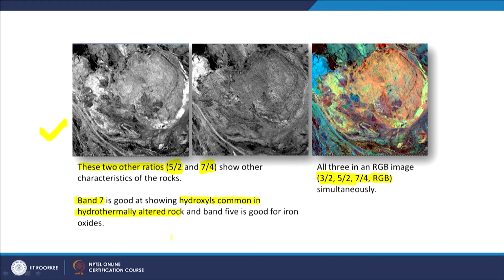Recall when we were discussing color space and false color composite and other things, those concepts which we discussed are being used directly here. So, that is why those things were also important. Now, one more band ratio technique, but not as simple as 5/2 or 4/7. There is a little more calculation, and that is a very standard index. There are many indices related to vegetation or snow cover and other surface feature identification, but the one which I am going to discuss is the normalized difference vegetation index.